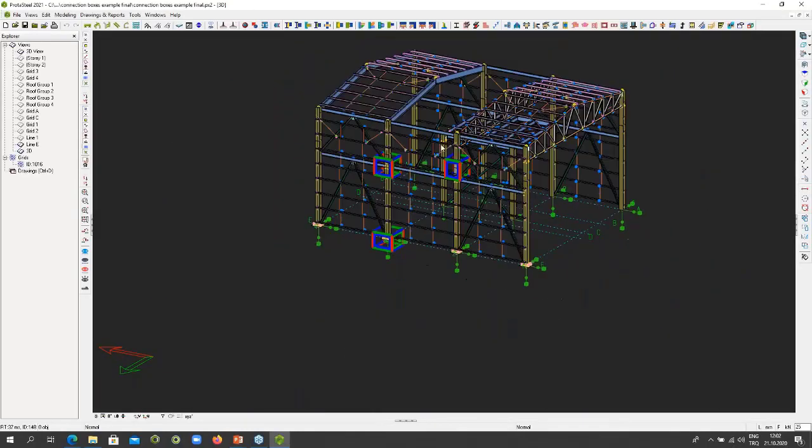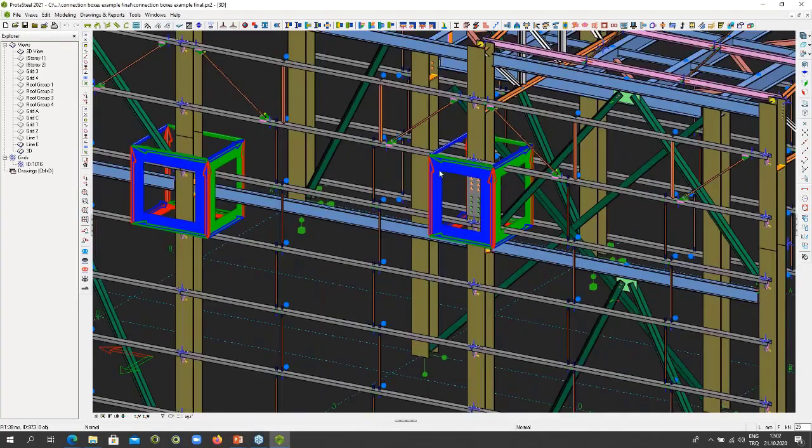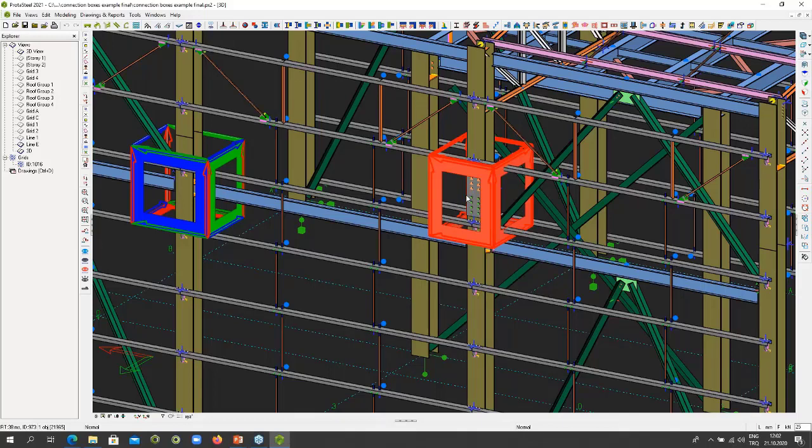So what we've added, which is new, is that previously, when we did this, we didn't have the option of joints. Now you have something called main joint ID over here, and this wasn't there before. We would only add the steel parts which would enter the connection and not the joint ID. But now we are adding a joint ID over here, and the reason is for what we call connection grouping, and I'm going to show you that in a minute. So just remember this box, and remember the fact that I showed you a joint ID.